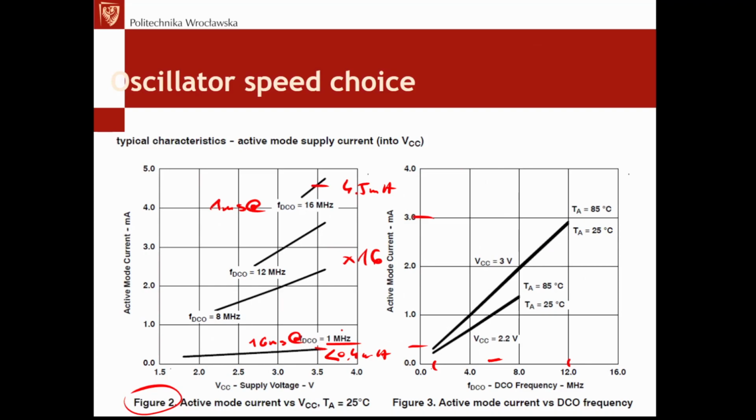So in case of microcontrollers, it's not really so important from this point of view to decide to scale down the clock frequency. Because if we put a microcontroller to sleep and we wake it up to do the job and then put it back to sleep again, then usually the highest clock frequency is the best. Usually it's the best, although at some situations it may happen otherwise.